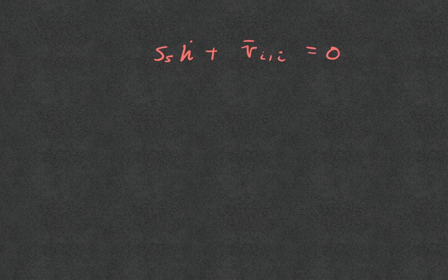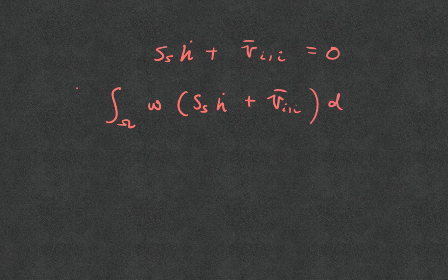Okay, now I want to convert into weak form, and the first thing I want to do is introduce integration there so that it becomes a global form, where I'm putting in the weight functions. This format, where I put a weight on the residual function, is called the weighted residual statement. This is called the residual. The residual is something we want to make zero. I put a weight there, and that becomes a weighted residual statement.